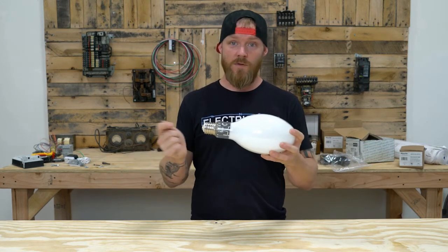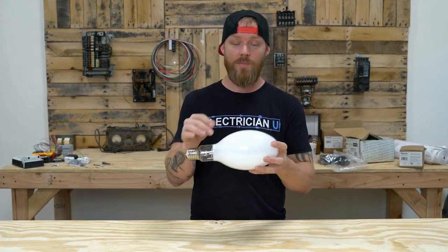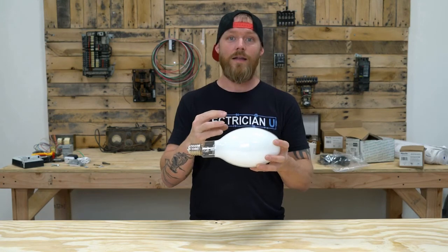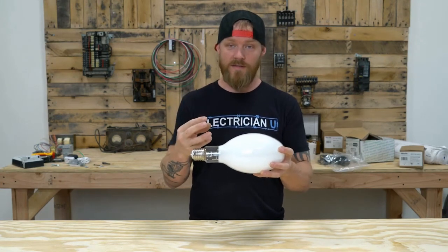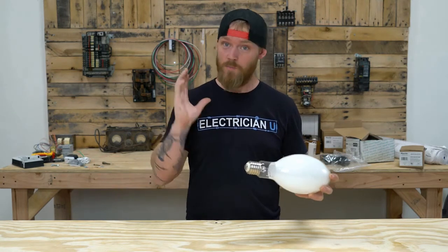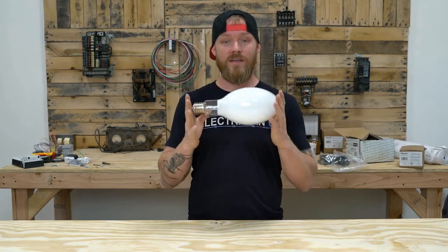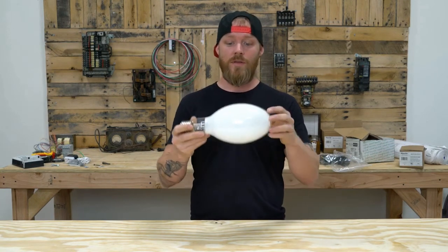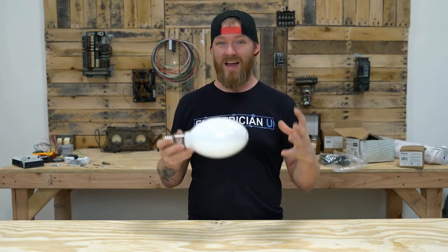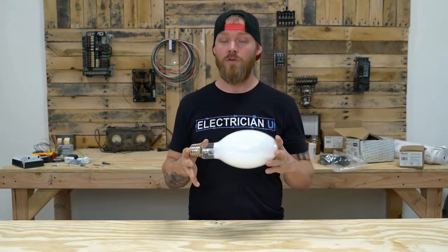So you still send this with a pulse, and you ignite an arc from the bottom electrode to the top electrode, and once that argon gas and that arc get hot enough, it starts to vaporize the mercury inside of it, which lets off a blue light. But everything stops there. It's just a blue light, it's just mercury and that arc, and that's it. So you'll see a lot of the clear mercury vapor, not the ones that have a phosphor coating like this, but a lot of the clear ones will burn like a hyper blue light, and they're like 6500 K on the spectrum, so really, really blue.